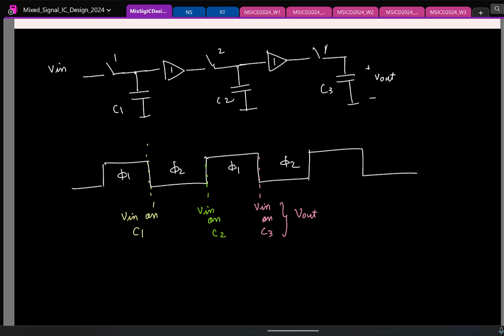It turns out we can do this by using basic interference. If you add signals with proper time delays and proper phase shifts, you will have constructive interference in some places and destructive interference in others. Which means you should delay the signal and add it with appropriate gains. That's the basics of constructive and destructive interference, right? For that you need a delay line, and this is one nice way of generating delay.